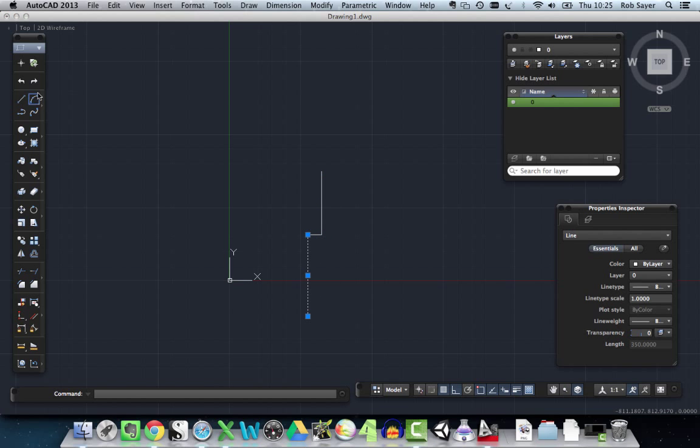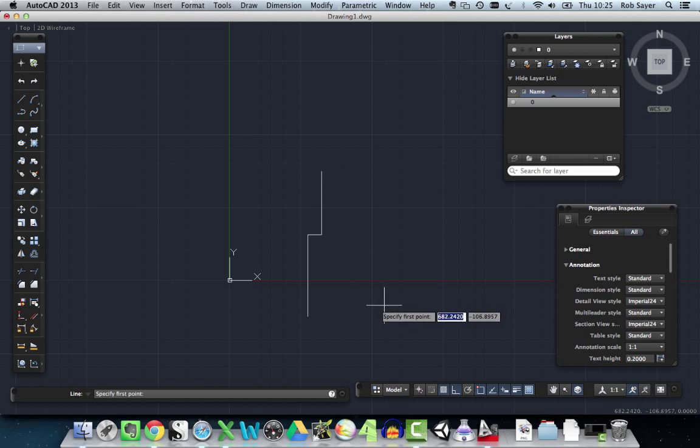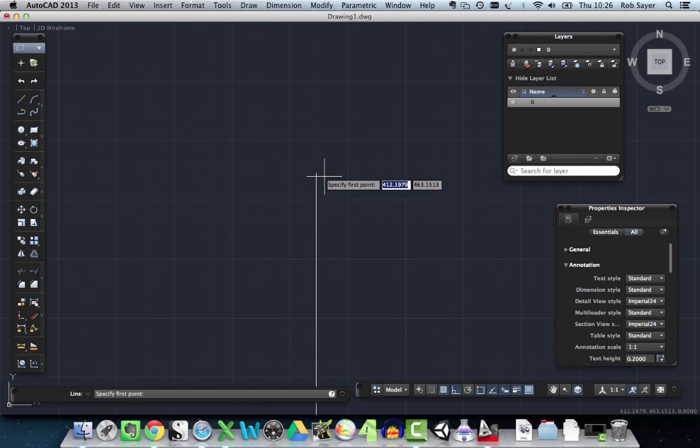If you remember what we did, we selected the line tool to start with. We started the point where we wanted to draw, and then we moved on from there. Now the other thing is, I want to carry on drawing here, so I want to be able to start from the point I just finished at. Luckily for me, there's a way to help me start at this point exactly. In CAD, this is called a snap, and basically it's like a little magnetic thing, so that when you start to draw, your cursor gets snapped to the end of something or the corner of something, or things that you want to draw from.